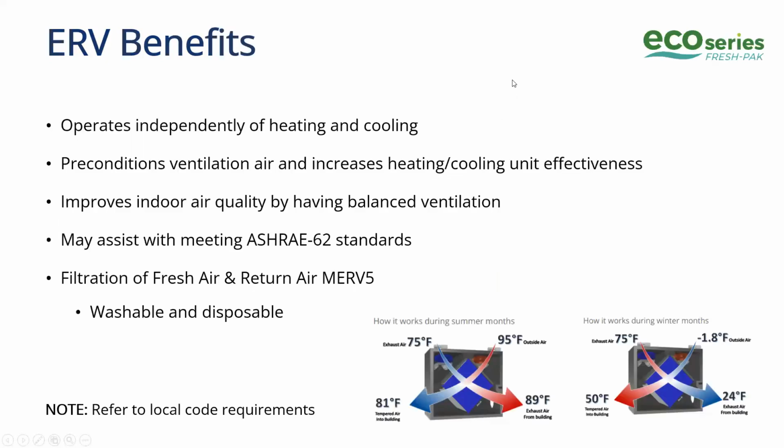I think we're all probably pretty familiar with the benefits of the ERV, but I'll go over it just in case. Basically, it operates independently of the heating and cooling. It's going to precondition that ventilation air, so it increases the unit's heating and cooling effectiveness. It improves indoor air quality by having that balanced ventilation. And it may assist with the ASHRAE 62 standards for ventilation for residential or commercial apartment type applications. And then we talked about the filtration of the fresh air and the return air being that MERV 5 filter.